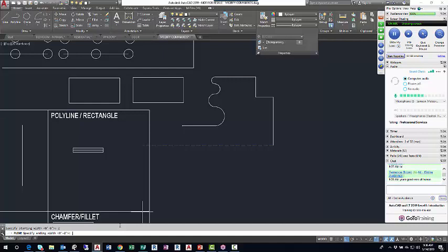Well, if I don't want a conical shape or an arrowhead shape, I'll use the same ending width, 2, and enter. And then there's this very bold polyline. Then I'll come down and click close. So there's a couple of the command line options that I use to create this nonsense shape, whatever it is.